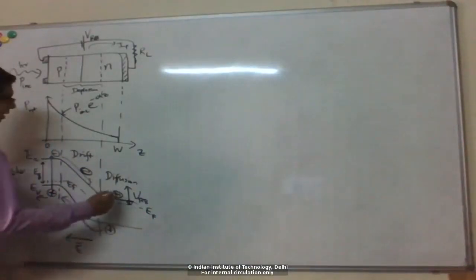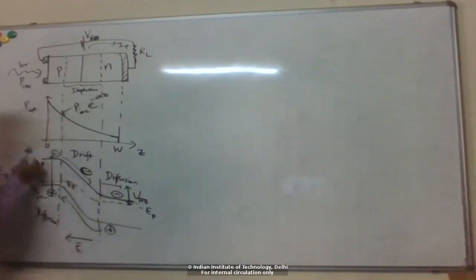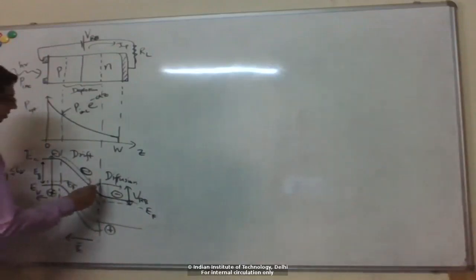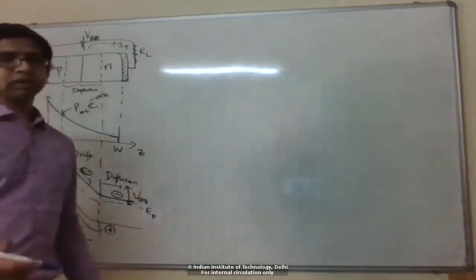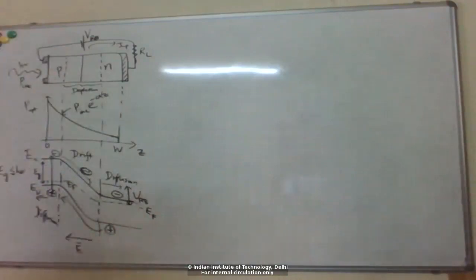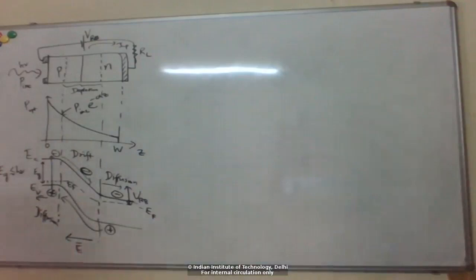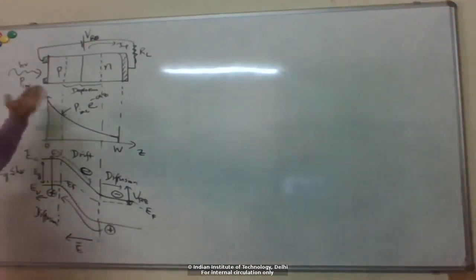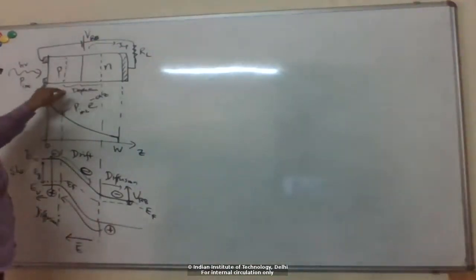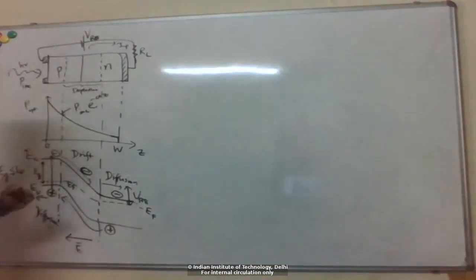Whereas here, if they're moving very slowly, even if you turn off the optical power coming from here, the remaining carriers will take a lot of time to diffuse out. So the device turn-off and turn-on time will be slow because of this diffusion. You can see straight away that what we want is that the depletion region should be almost the entire width of the device, right?